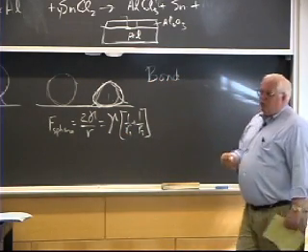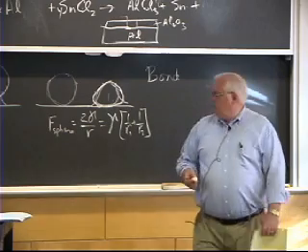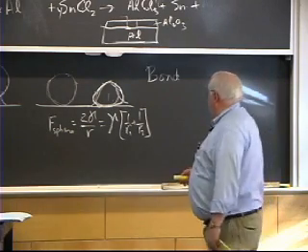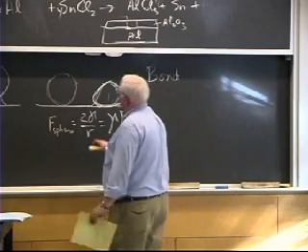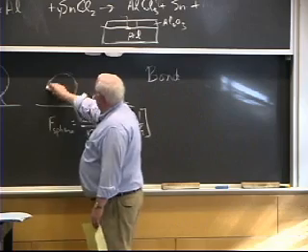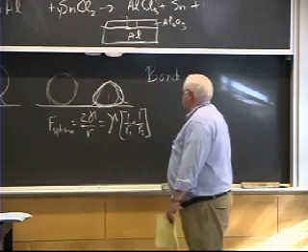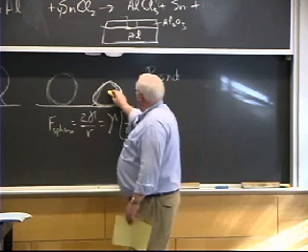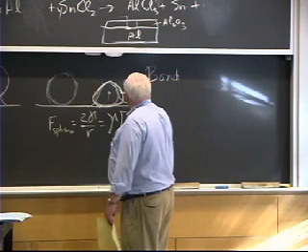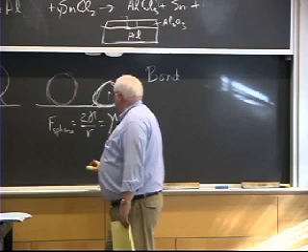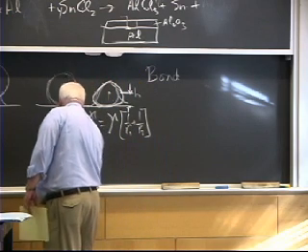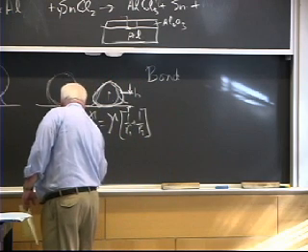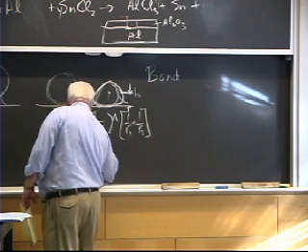That's the thing that wants to make soap bubbles spherical. That's the pressure force that wants to make a solder ball, a nice small solder ball. And then the gravity force, if I have some average height h, which is trying to pancake it, is rho g h.